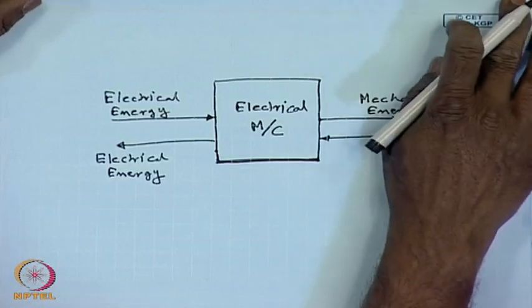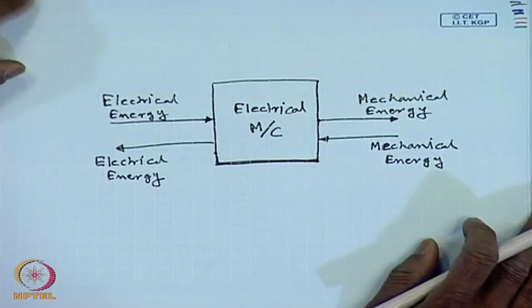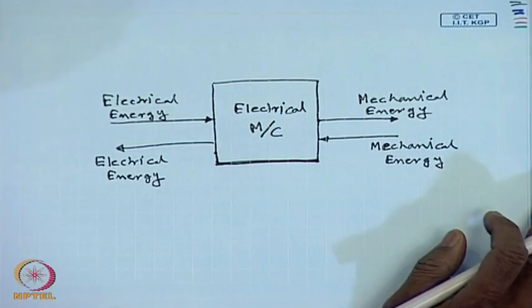Now, invariably almost all electrical machines are of rotating type. I said almost because some are not. The reason is very simple, one of compactness. In order to either accept or give out mechanical energy, there has to be some motion of some physical object of the machine against an opposing torque.